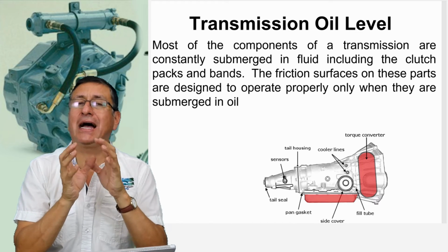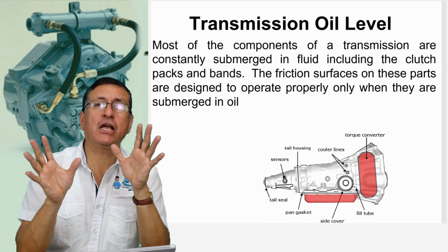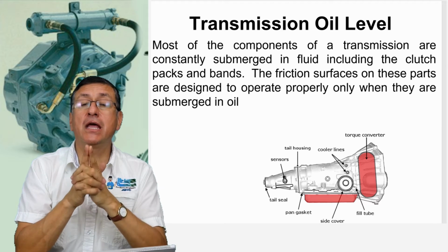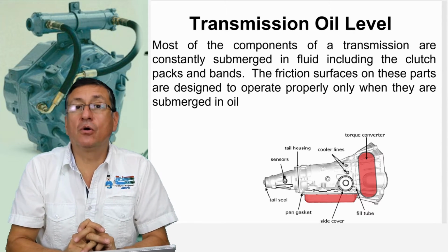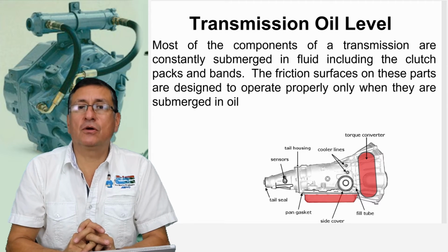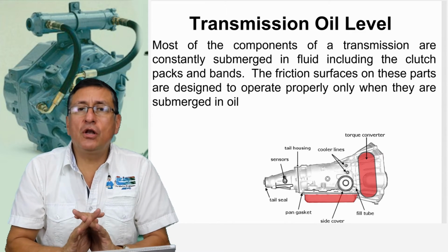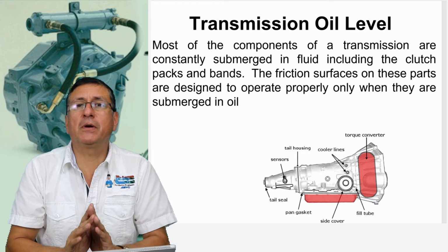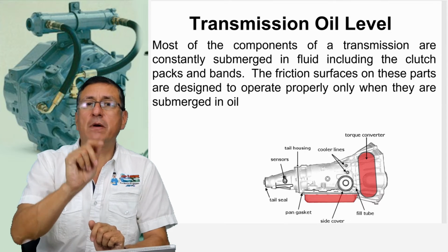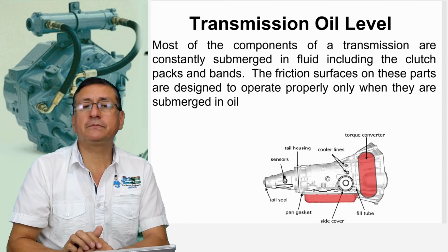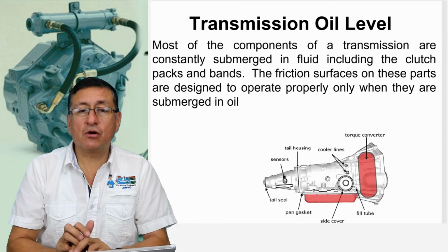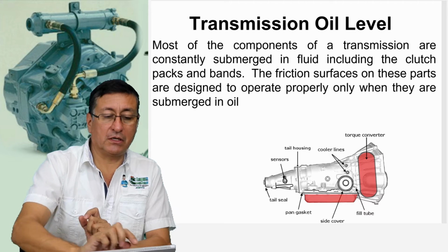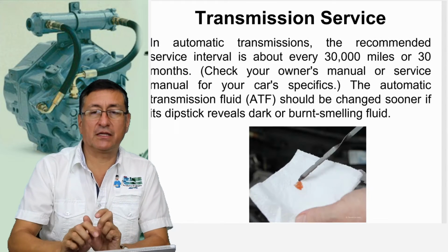Never use a generic oil. Be careful with generic oils, especially in transmissions. Those generic oils damage those transmissions. Use only the fluid recommended by the manufacturer in the service manual. Check the service manual and try to flush the oil according to the intervals recommended by the manufacturer. That's the service, no? The service that I explained.